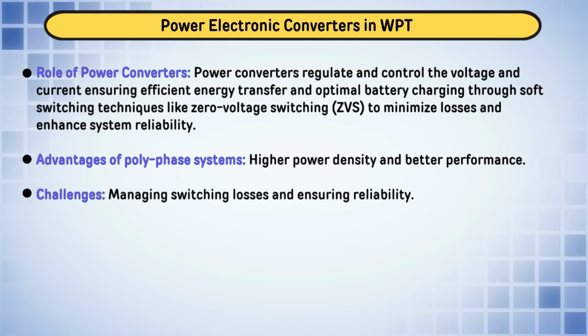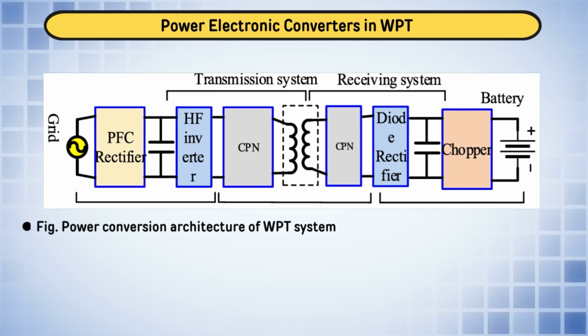So, why the dual active bridge converter? It is a bidirectional converter. It can offer the feature of bidirectional power flow and utilizes a high frequency transformer. These switches can be operated at very high frequency, and there is a reduction in transformer size. It has high power density, which is suitable for grid integration and battery charging applications. It can provide galvanic isolation, and there are fewer components.